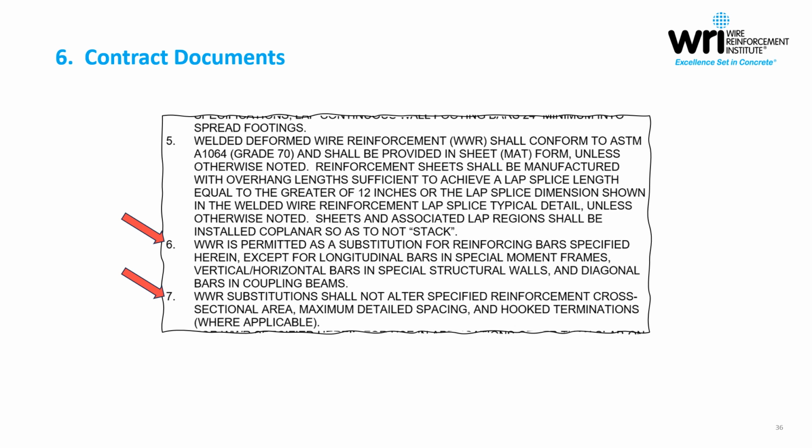You know, if you're detailing rebar, number 4s at 12, you don't want a welded wire reinforcement equivalent that's using spacing in excess of that. Now, I will say that most welded wire reinforcement detailers know this, know not to exceed the detailed spacing. They've been doing it long enough, they have the experience. But it's always a good idea to kind of establish your ground rules.